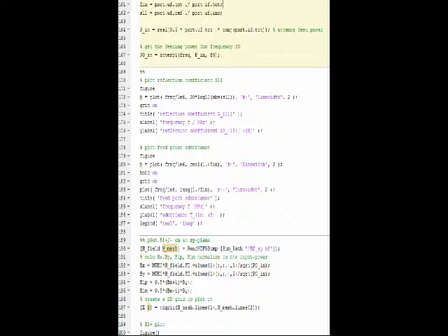After that, we are going to plot all the variables and all the magnetic fields we are interested in. Here we set up the frequency. F0 and Fc refer to the center frequency and corner frequency respectively. F0 minus Fc refers to the minimum frequency. F0 plus Fc refers to the maximum frequency we're going to plot. 501 refers to the step size. We maximize the step size to 500, therefore we will get a better result.